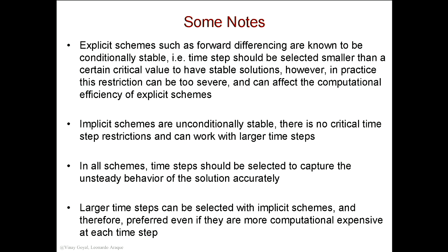In implicit schemes, you can select larger time steps, but at the expense of a little more error than you would have liked. However, implicit schemes are more computationally expensive because you have to invert the stiffness matrix over and over again.